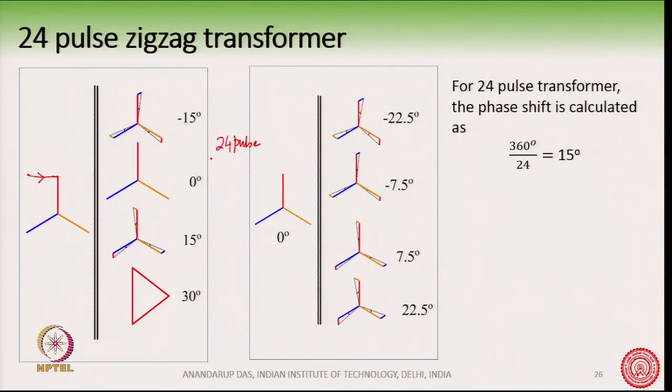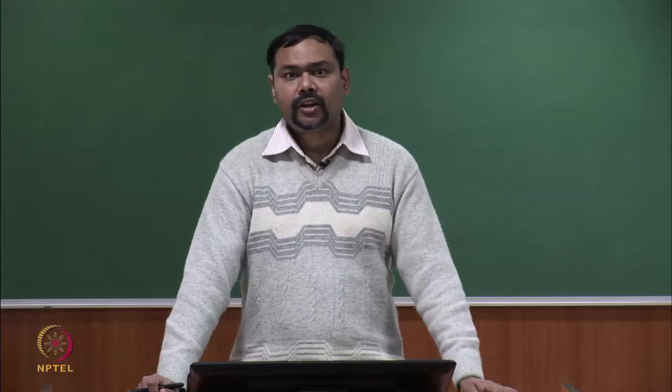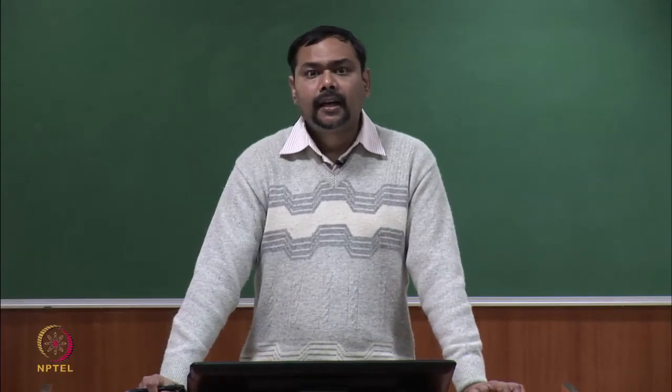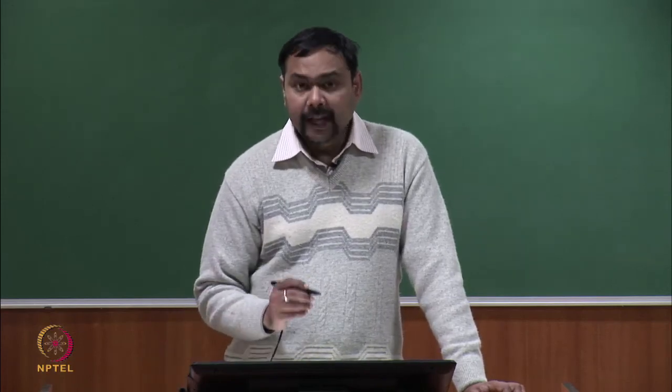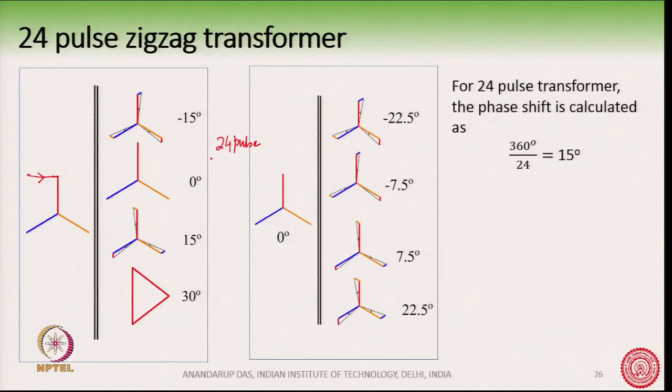The stress on the transformer for a more symmetric arrangement is less. In particular, during short circuit condition of the transformer, there is a stress on the transformer due to the short circuit current, and the mechanical stress on the windings can be more symmetric if we have a more symmetric output on the zigzag transformer. So, preferably this connection may be used.